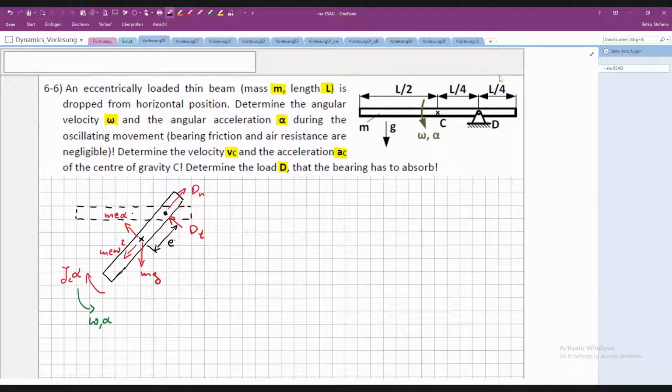Yeah, that's what we discussed in our last class. Our general approach for the general motion of an object always includes the inertial forces in the center of gravity and the inertial moment with respect to the center of gravity. So if we always break it down to these two parts, inertial forces in the center of gravity and inertial moment with respect to the center of gravity, this fulfills the requirement for any arbitrary motion.